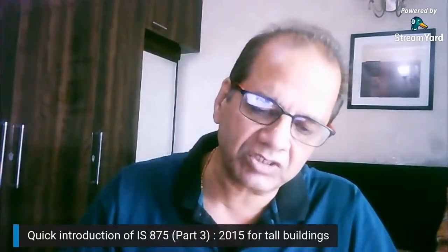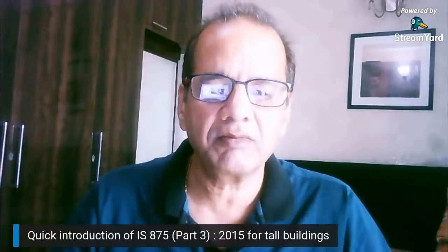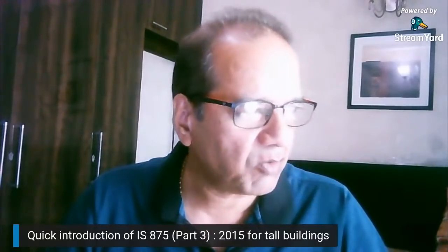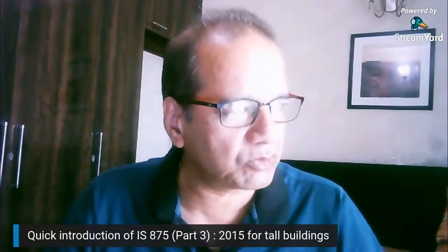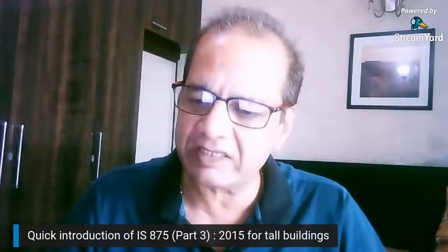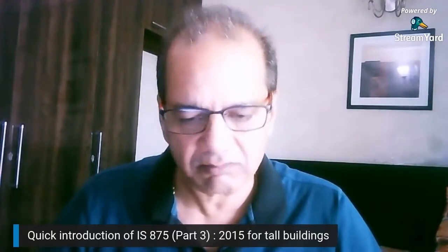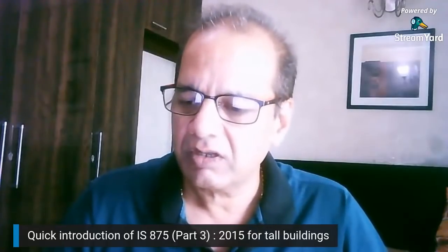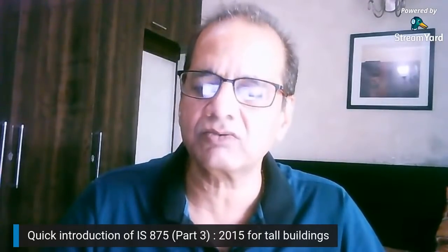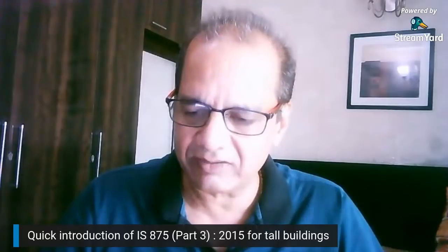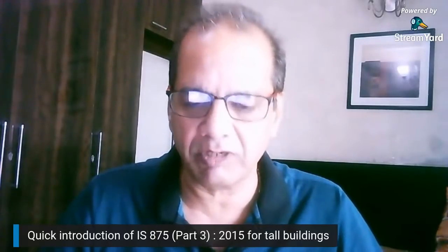The next section in the code is about the definition. What should be a tall building? So a height to depth ratio has been given and a natural frequency less than 1 hertz has been identified to be qualifying as tall building.